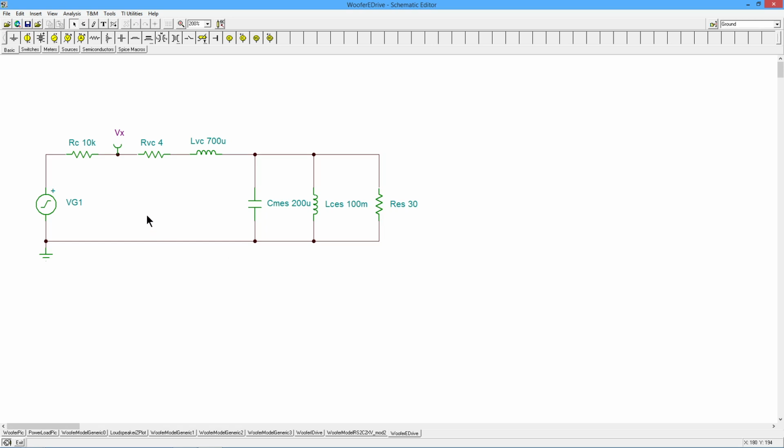Now, if you don't have a scope, you might be tempted to say, well, I'll get a DMM and I'll measure the voltage that way. I have to caution you about that. Unless you have a fairly high-end DMM, it's not going to accurately measure AC at higher frequencies. A halfway decent meter will go up to about 1 kilohertz for AC.